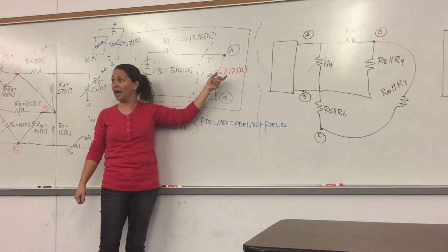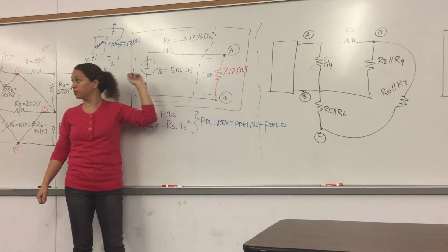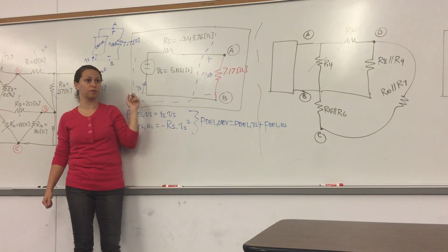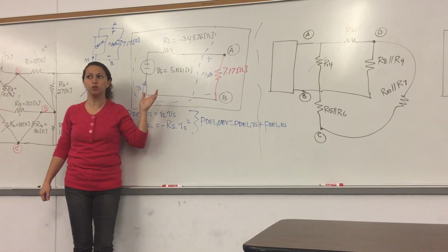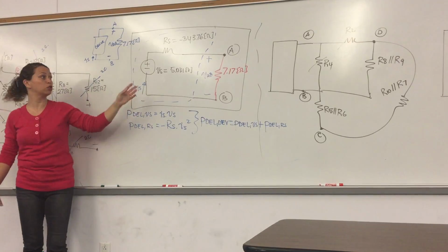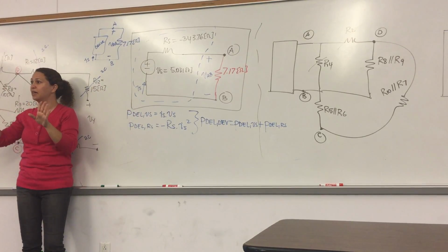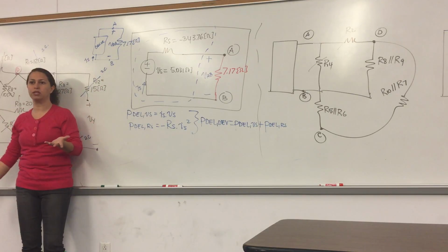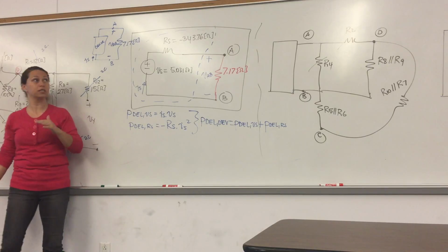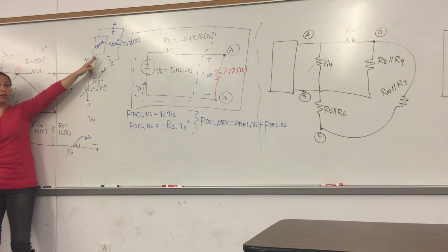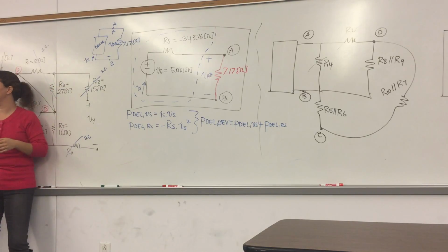That's power absorbed by that, which has to be equal to power delivered by the device. I think that's the easiest way to go. But that's just because you have 2 components here, just a device and another component. Otherwise, you wouldn't be able to do that. Let's say you have tons of other components, you are looking for the power associated with the device. Your best approach is to label the voltage across the device, current through the device, and then find what it's equal to. Okay?